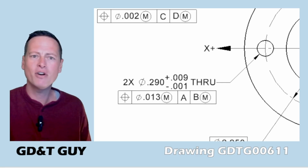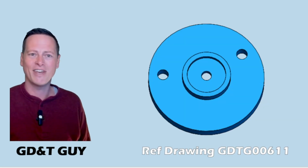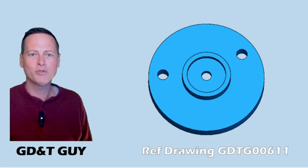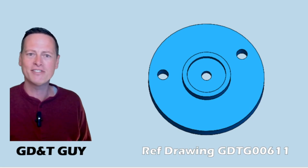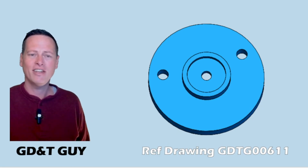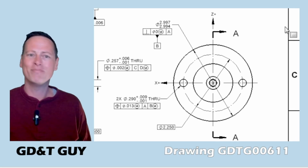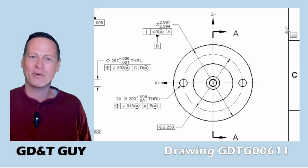But since there is no feature that constrains the part in rotation, there is no tertiary datum here. It's seen as irrelevant. Well, you say, wouldn't I then have to accept a part that has its holes poorly located to each other like this? Since I'm free in that last rotational constraint, isn't it like anything goes where I place these holes in rotation? Nope, that is not a thing you would have to worry about.